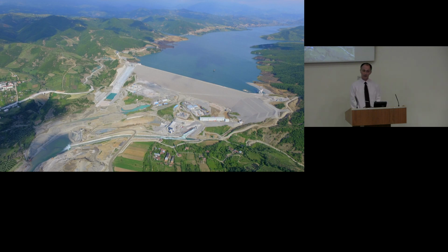Ballpark, because don't forget, it's not our design. It was AFC's design, and we were just implementing it on site. I think they were either 4, 6, or 8 meter long bolts, and the spacing would have varied a little bit, from probably 1.5. In the most intense area, we had bolts at really quite close spacings, up to random bolts at maybe 3 or 4 meters apart.